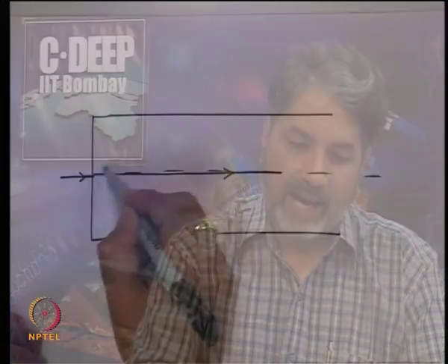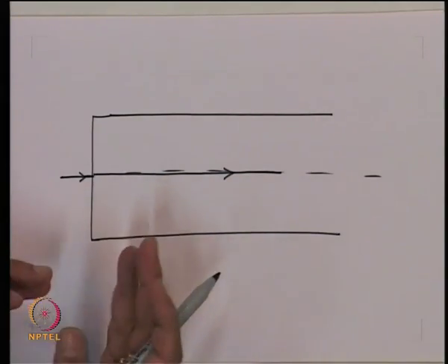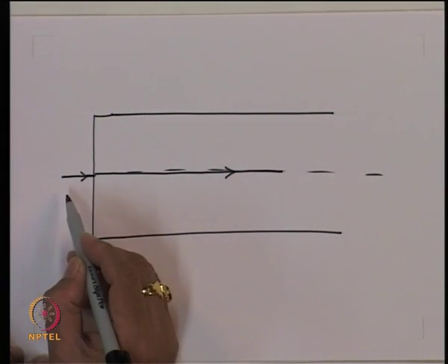And if I want the rays which are going to the higher angles to travel faster, essentially the refractive index must reduce for a region which is somewhere here, and the refractive index should be highest here.